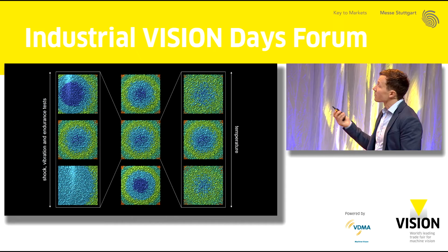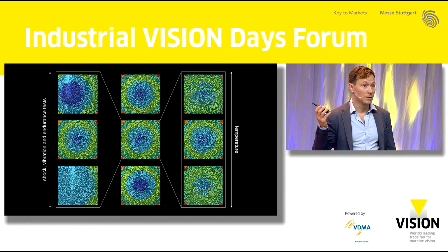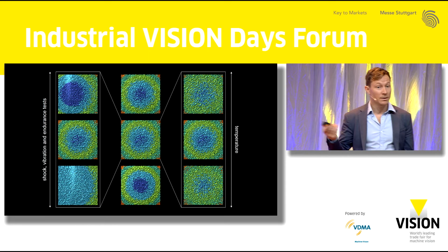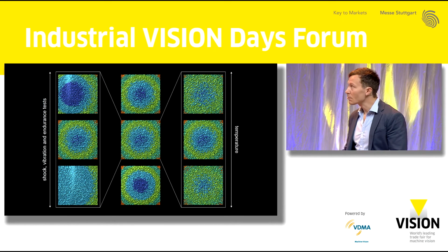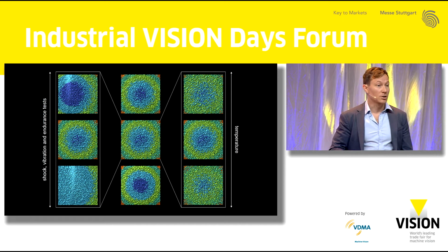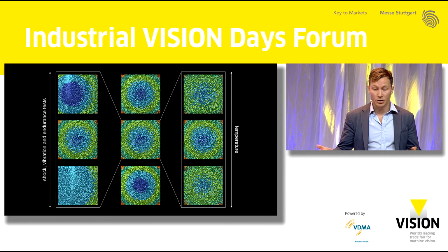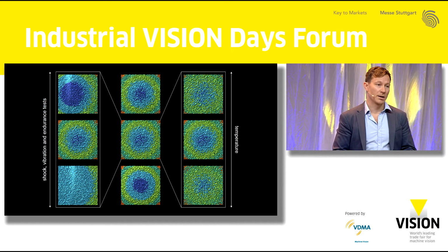But we can't really stop there, because a 3D camera is a mechanical, physical device, and they have atoms. And atoms react to heat, for example. So what we do is we repeat this measurement across different temperatures. We change the temperature to maybe 5 degrees centigrade, or 20, or 40 degrees centigrade, and we repeat the whole shebang.